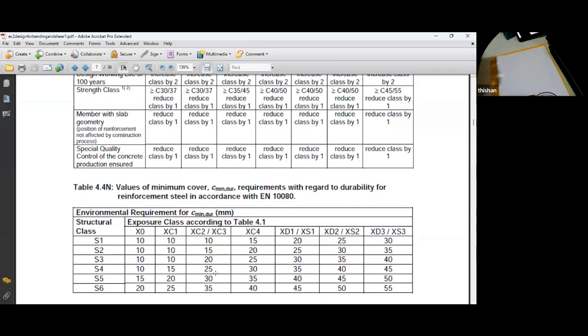If you are not precasting, 25. But when you are not precasting, better to have the tolerance 10, 35. But if you are going to verify, again you can go for 25. Because cover is the main reason for durability. So Eurocode identifies this very clearly, and they have placed a lot of emphasis on the cover, especially for people doing construction haphazardly, not paying enough attention to the cover, where they don't use proper cover blocks, they don't keep enough cover. For such situations, Eurocode is very specific.